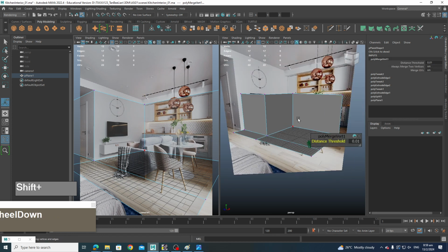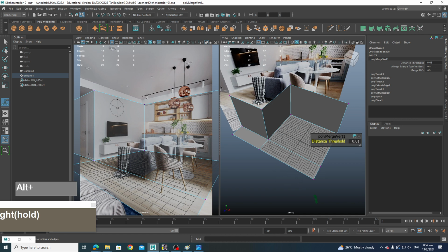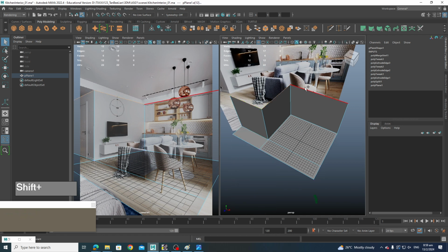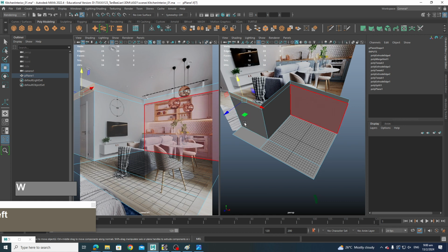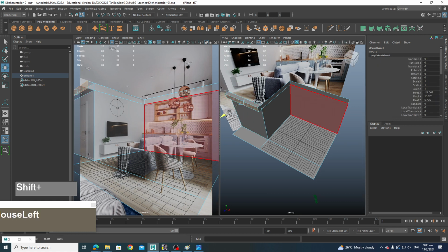Okay, and then coming over to perspective view, select all these entire edges on top here, and then extrude out another section. So Control E, press W to move. Just let it extrude up like that. Okay, right now I'm reaching the ceiling already. Now I have this extra face over here which I can extrude, holding down the Shift and then extrude outwards like that.